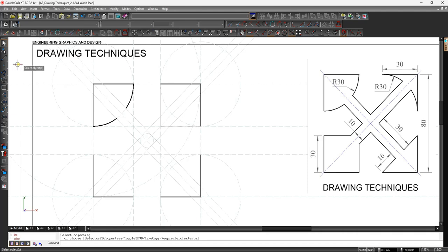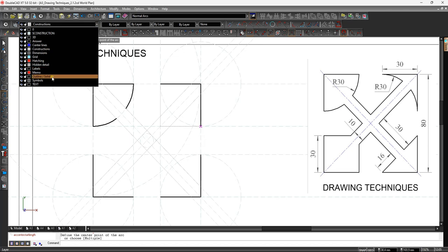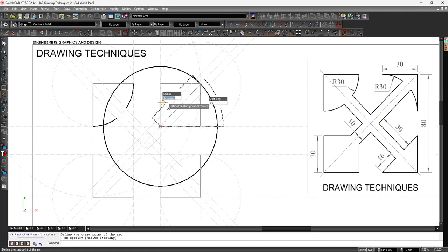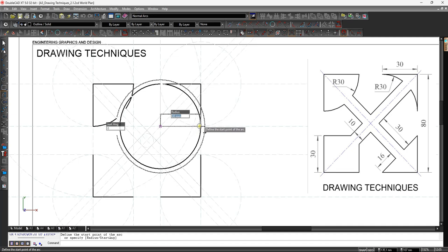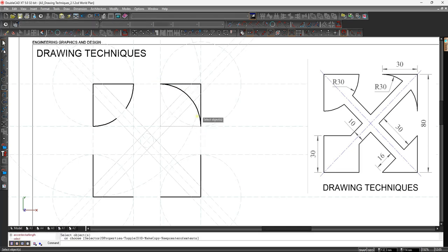And now I'm going to go back to my arc tool, and I'm going to make sure I've selected the correct arc tool, and I'm going to go to my solids layer, and then I'm going to place my compass on paper and in CAD on this intersection that I've created, and I'm going to stretch it. Remember, it's working anti-clockwise, so I have to go to this reference point, and I'm going to click on that and draw the arc to the alternative reference point. So once I have that, I go again to my split entity tool.